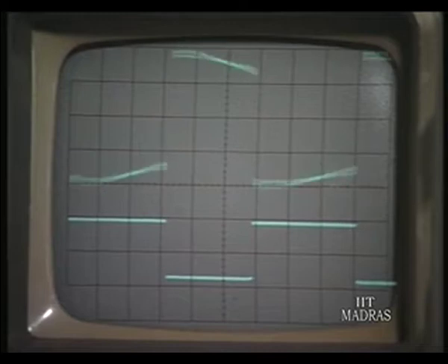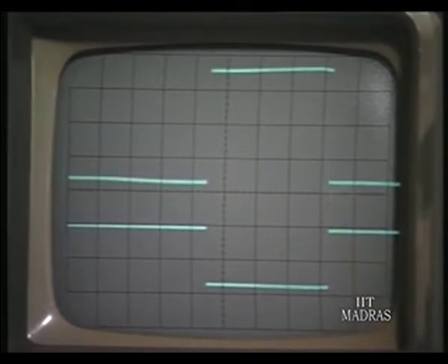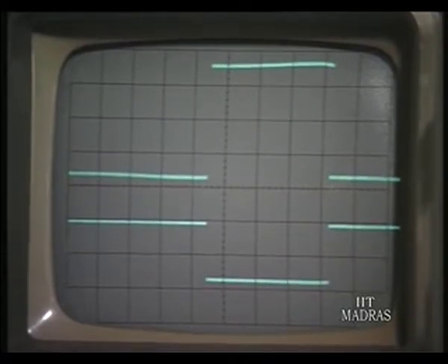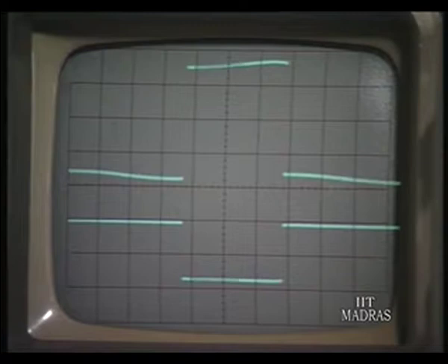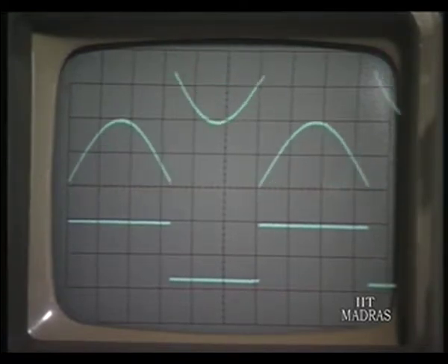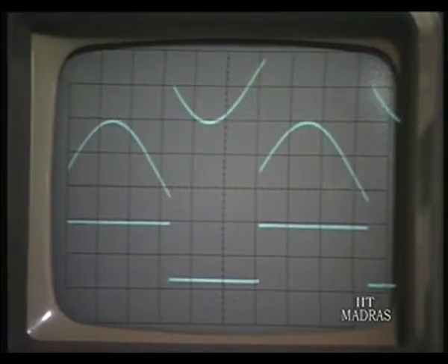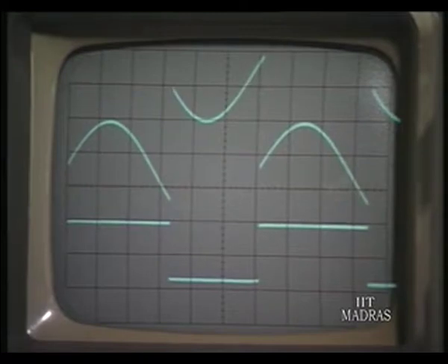Please show the thing, change the frequency. Now, the output is simply the square wave. On either side of omega naught, output of the notch is a square wave, right. So, it has not eliminated anything at all, and therefore, output is simply a square wave for an input which is a square wave. This is a notch filter. It is going to be really tuned only when it is tuned exactly to the omega naught of the filter, it will remove the fundamental and not otherwise.